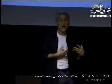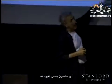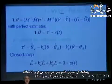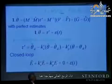No, friction. There is actually nonlinear friction that is difficult to model, and there are a lot of other nonlinearities, and then you have the higher order dynamics that we are not modeling. We are modeling just second order dynamics. The flexibilities are not modeled. So you are going to find limitations here. You can try to compensate for part of the friction forces, but it's not going to be perfectly compensated for. So higher gains are very important here, in practice.